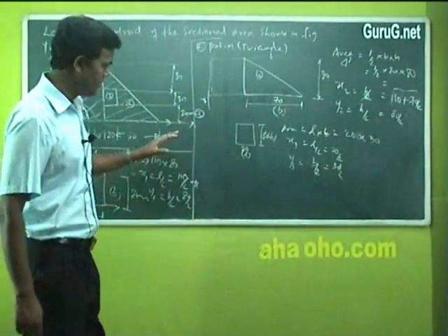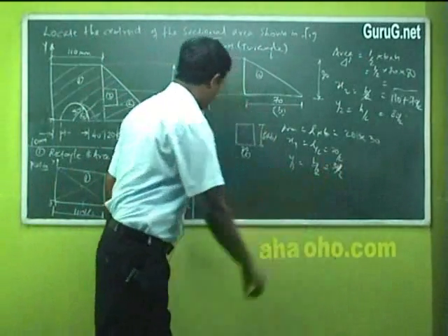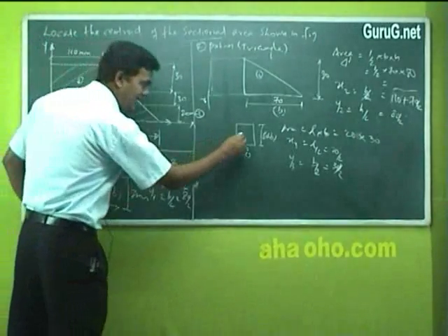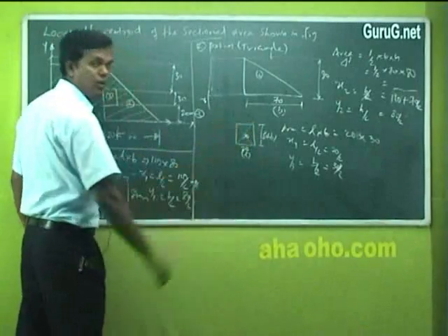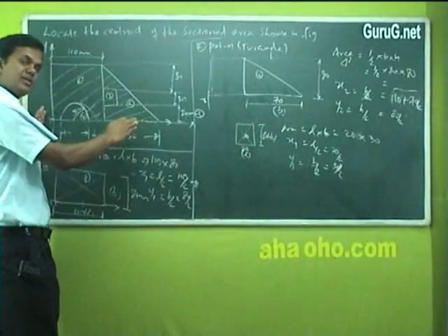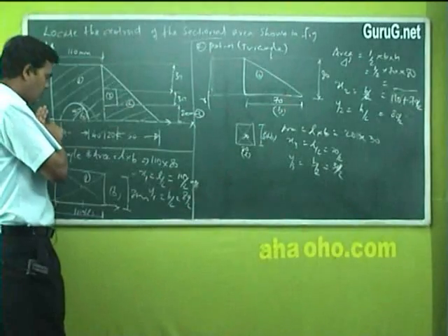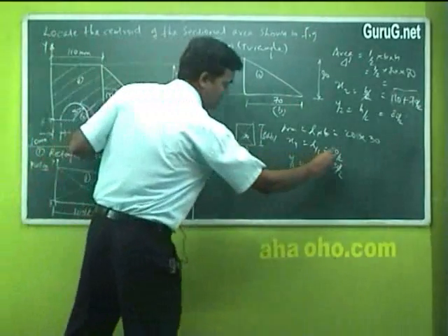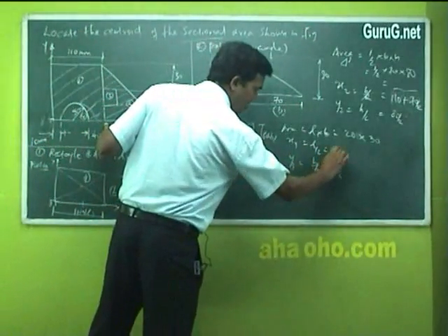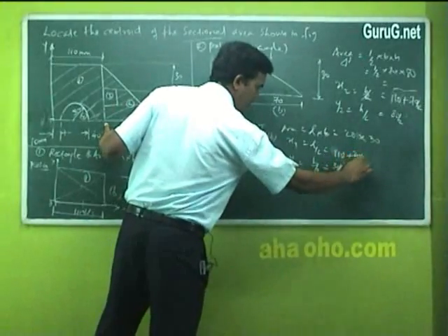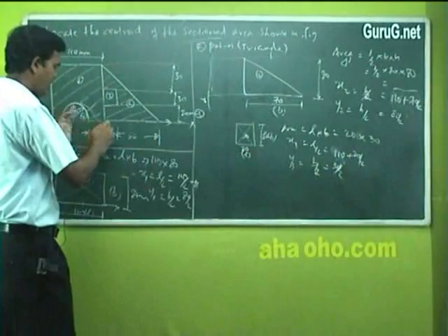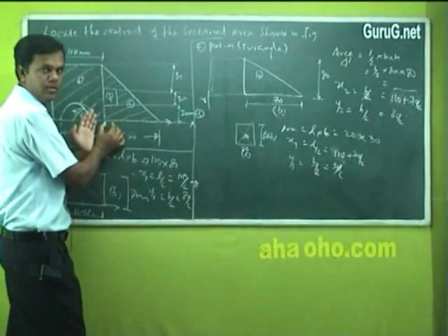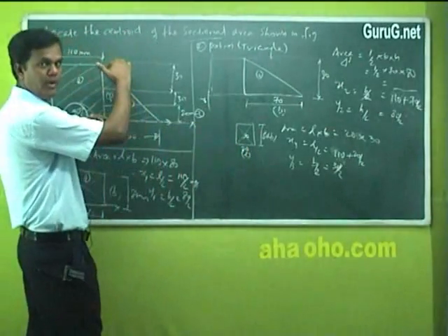Again the same question: where did we start? For this diagram inside here, for the x value, that means the center point of this rectangle, I am trying to find out. So for the x-axis line, I start from the O. It is the base. From O, I traveled 110. Then I find out this center value. That means this 20 by 2, it should be 110 plus 20 by 2. I hope you understood. I am traveling 110, then finding this center value, this distance.